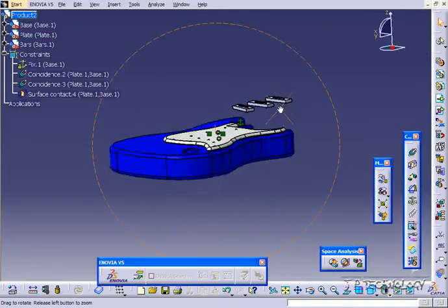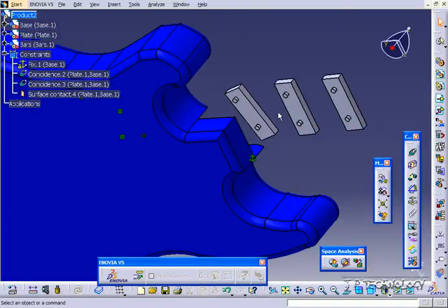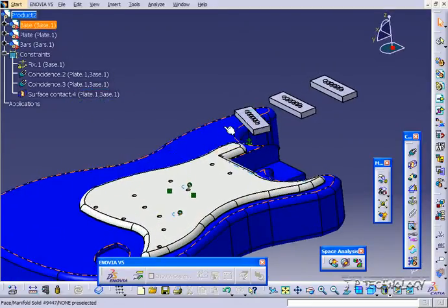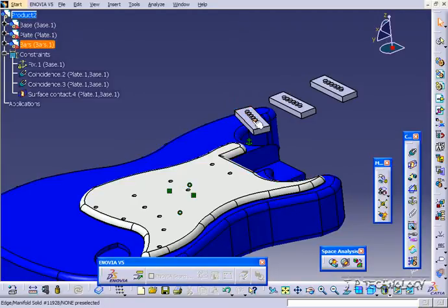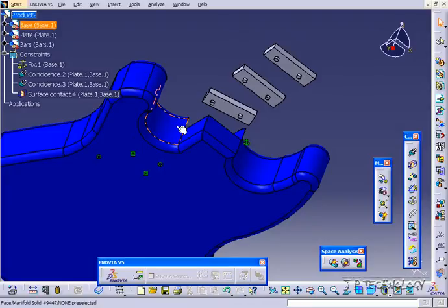Click OK. Now if you look under here, there's 6 pilot extrudes that I made, and on the plate there's 6 pilot holes. Now when positioning this though, because rather than having individual parts for each one, I made it in one part, all we have to do is use 2 holes to position it. Whenever there's multiple holes like this, and all I need is 2 holes or extrudes to position, I'm going to pick 2 that are on a diagonal from one another. By choosing 2 that are on a diagonal like that, you're able to position and lock it in.